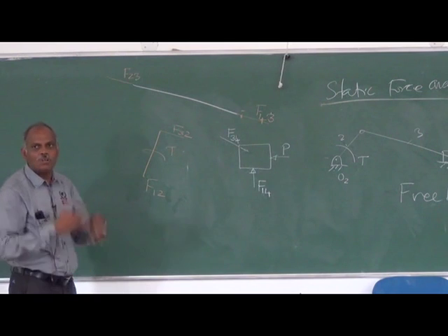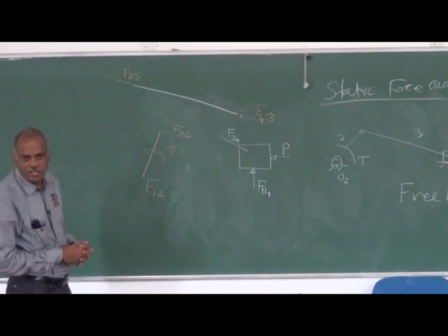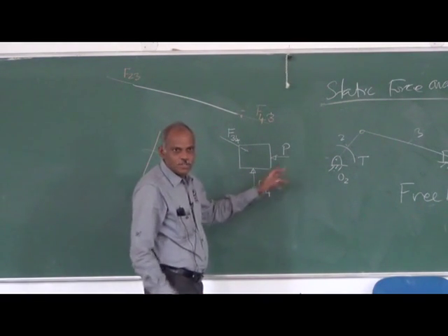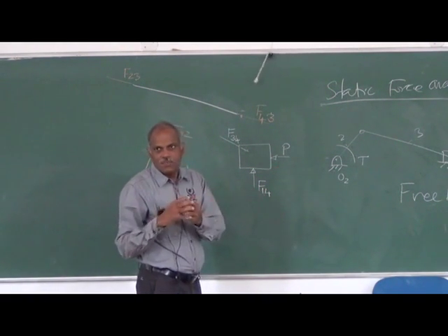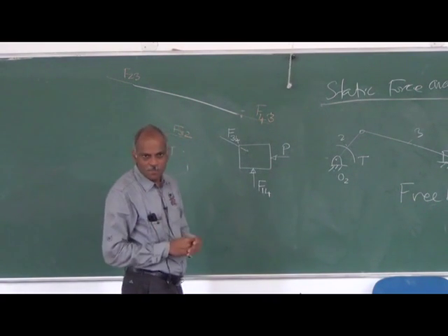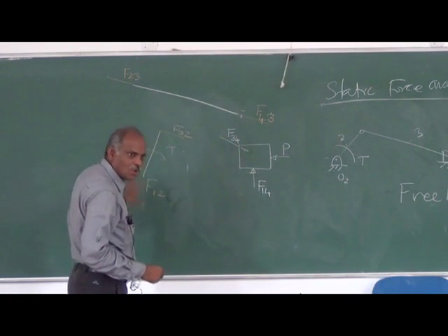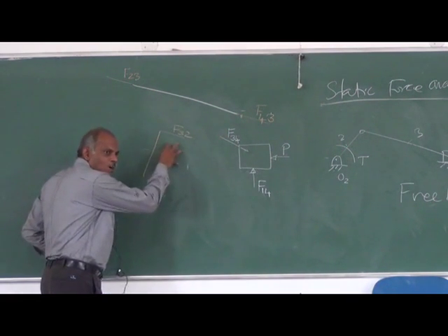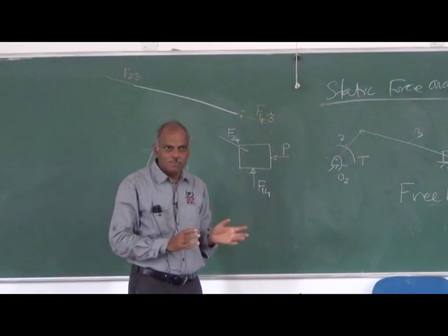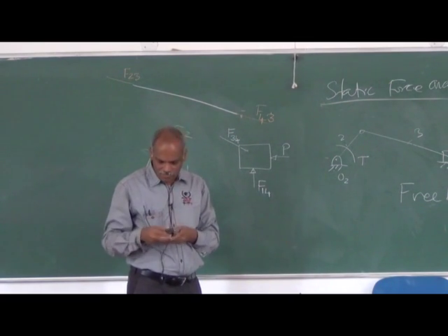So I have to draw the free body diagrams of the three linkages and solve, where P is known. Use the various engineering mechanics principles that you know, then solve for the magnitude and direction of each force. Then you will find out the holding torque T. That is our job in static force analysis.